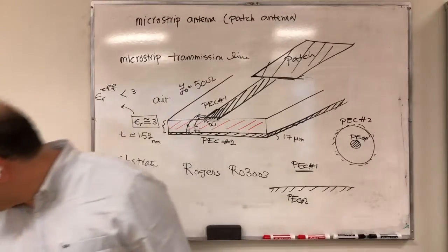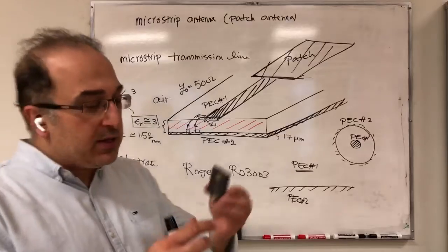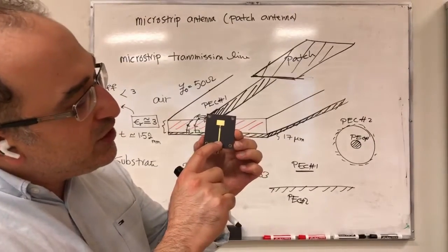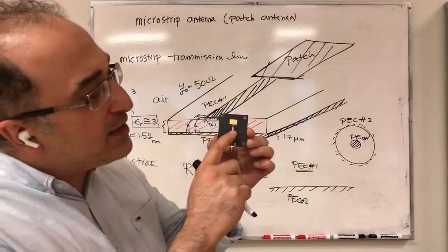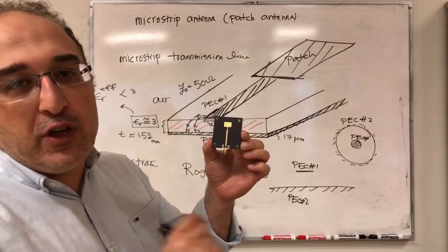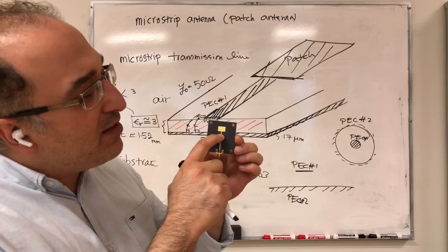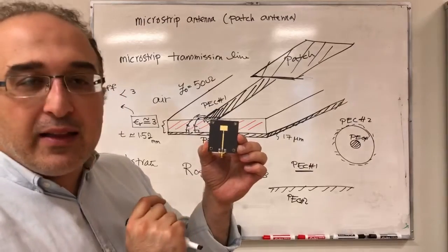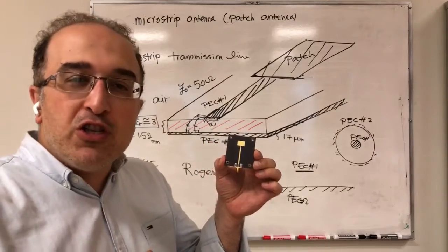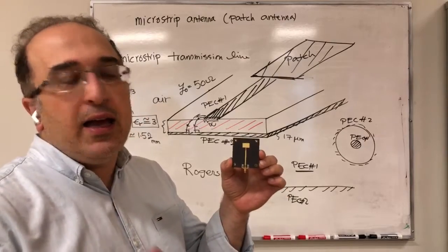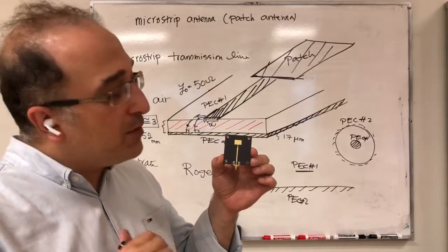Now if I go back to this microstrip antenna, the initial width that this antenna starts with is for 50 ohm at the frequency of operation. And you see the line gets thinner right after that. That means now you're switching to a different characteristic impedance, so that's something to keep in mind.